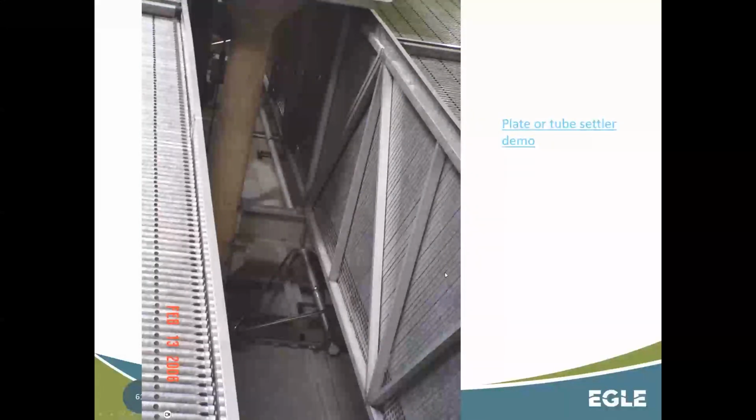So the magic is in these plate settlers, the mechanism that makes them work so efficiently. You'll notice on the vertical column, the sediment or the particulates had to drop the entire length of the vertical column before they were settled out. On the inclined plate settler, they only have to drop basically the width of the tube before they hit the bottom. And once they come into contact with that surface, they start piling up on top of each other, and they start sloughing off down those stainless steel plates. And the speed at which they slough off down that surface is much faster than the rate that they drop through the water column.